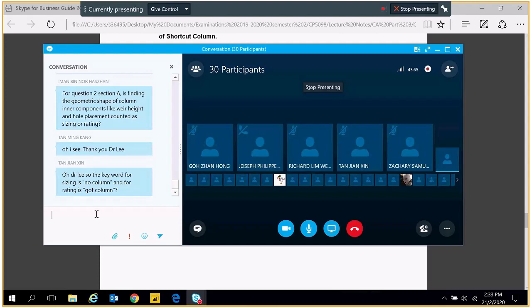As I mentioned, we got a problem with fouling. So you suspect there's fouling on many trays, and therefore the purity of the benzene is no longer 96 mole percent; it is below 96 mole percent, maybe 93 or 94 mole percent. Because we suspect that, we do a rating. When we do a rating, in fact, our hypothesis is that the separation efficiency has decreased. So we do a rating, and from a plot we know the K factor. Remember y equals Kx. You look at the K factor.